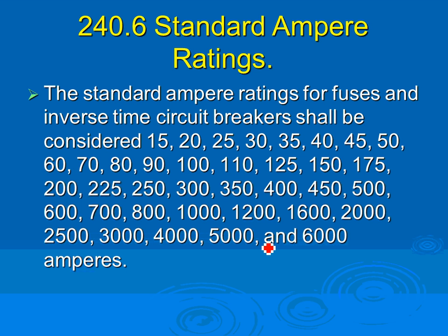So how many of you went to a 3,000 amp service and measured the actual current and found 3,000 out of it? Did you? There's a factor called the load factor: after you design everything, you go measure the actual current, and your load factor is typically between 30% and 70% of your design.